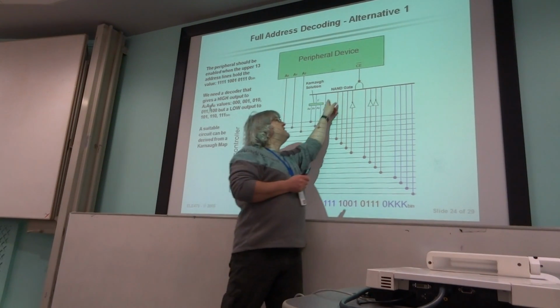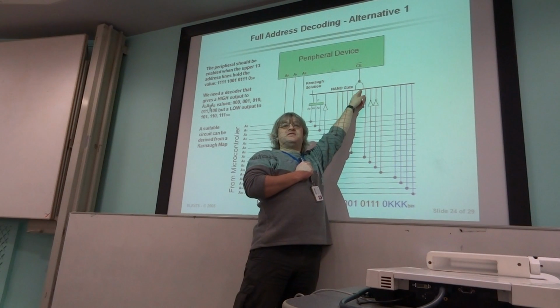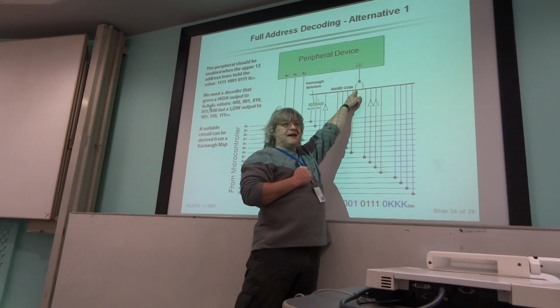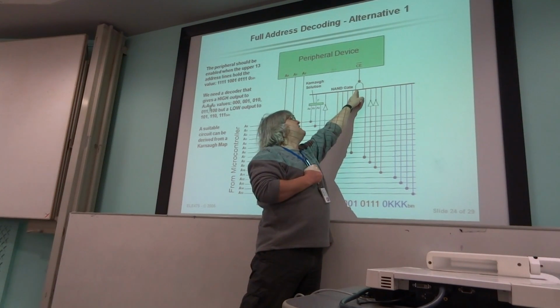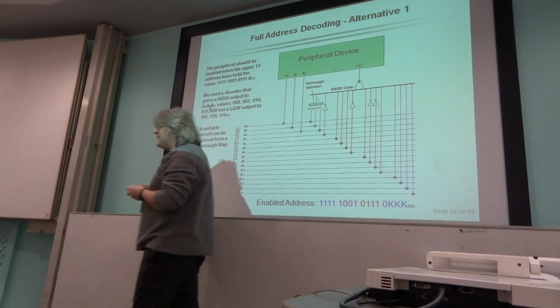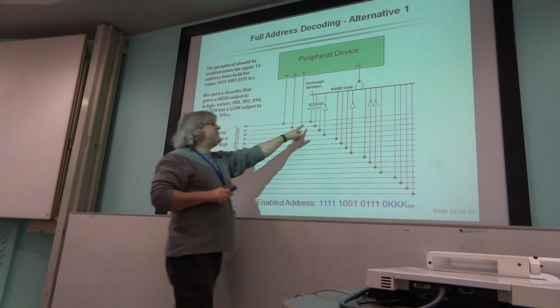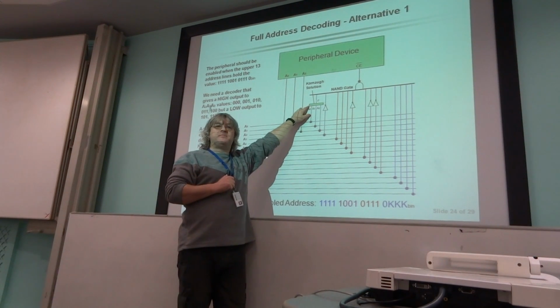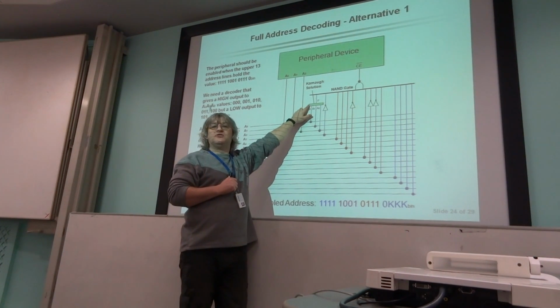It's still not a simple design, but now instead of 5 16-input AND gates followed by a 5-input NOR gate, we've simplified it down to a 16-input NAND gate, a few inverters here, and we're going to use a bit of year 1 Karnaugh maps to come up with some simple combinational logic to put in here.